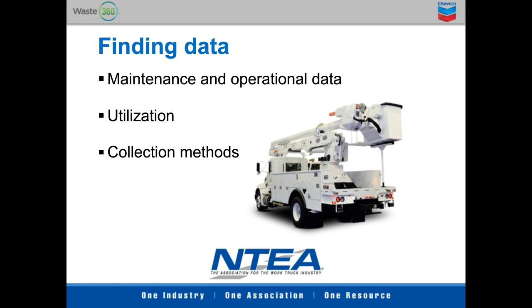If you're a small fleet, the most basic thing is fuel records. That gives us how much we're using vehicles. Maintenance records. Again, we can start looking at trends for component failures. Let's replace these before they fail. Let's actually design a preventative maintenance schedule based on usage. A lot of times, it was simply we did maintenance when vehicles were available, but now we can actually schedule.